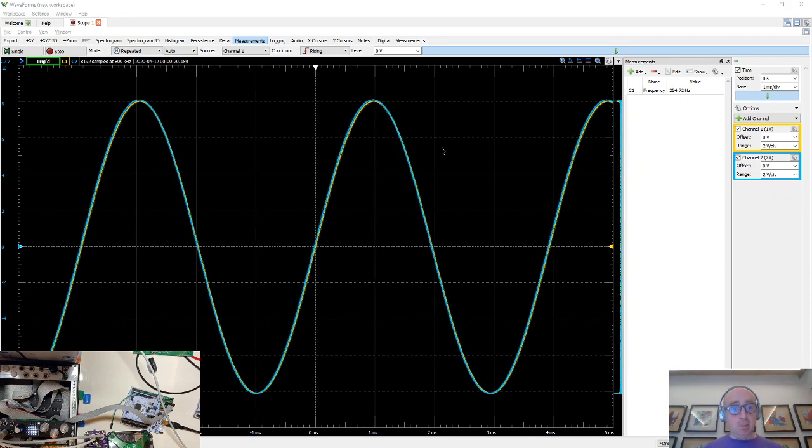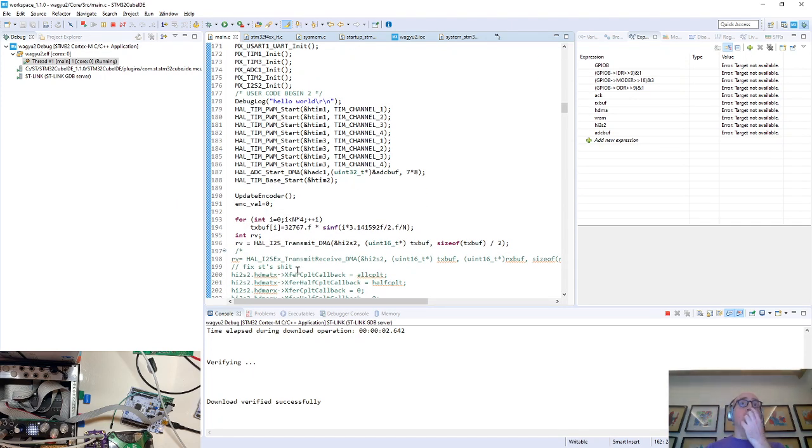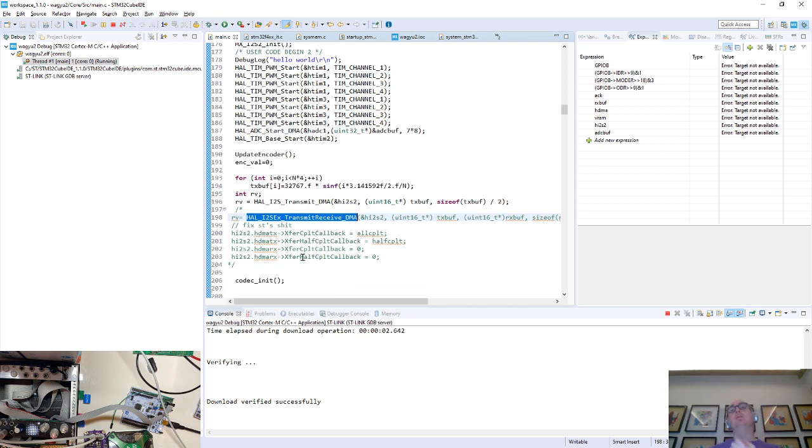And I'm just going to wrap up my entire stream by saying to do receiving, you basically call this function. And my rage is manifold. First of all, this function is not in any of the samples. So this is hardly documented. And it's in a different library. It's not in the I2S library. It's in the I2SEX library, which probably makes sense to the people in ST.